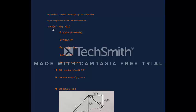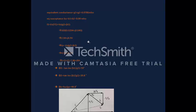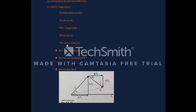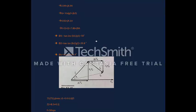I1 is equal to V naught into Y1, which is also equal to V naught into G1 plus JB1, as it's the whole admittance part. As we see in the calculations, it turns out to be 2.94 plus J4.94 amperes. I2 is V naught into G2 plus JB2. Similarly, we get the current after calculation to be 7.86 plus J9.9 amperes.